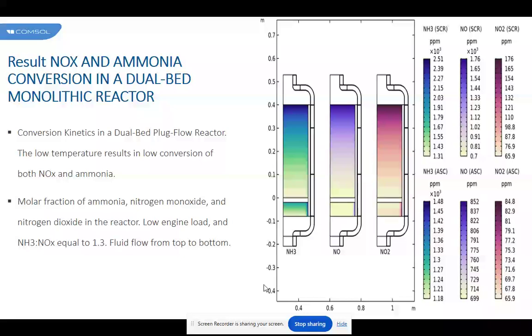To investigate the impact of using a dual cell substrate on conversion efficiency, pressure drop, and fluid distribution, the substrate is divided into two concentric regions. One is at its core and one at its periphery, and a different cell density is given to each part. According to the results, a difference of 40% in apparent permeability is sufficient to lead to a large mass flow distribution, which impacts conversion efficiency and pressure drop.